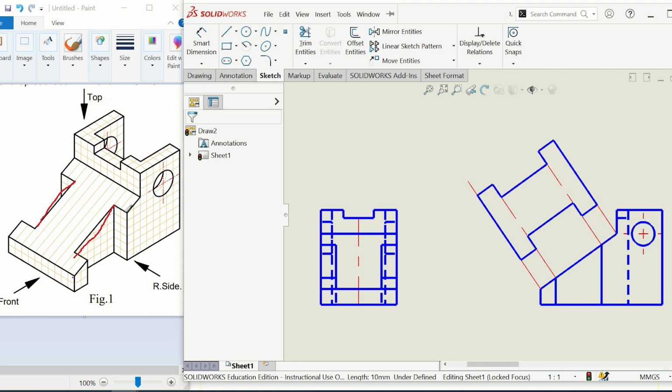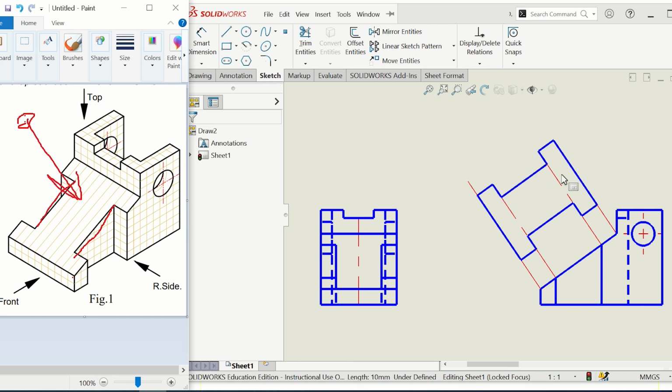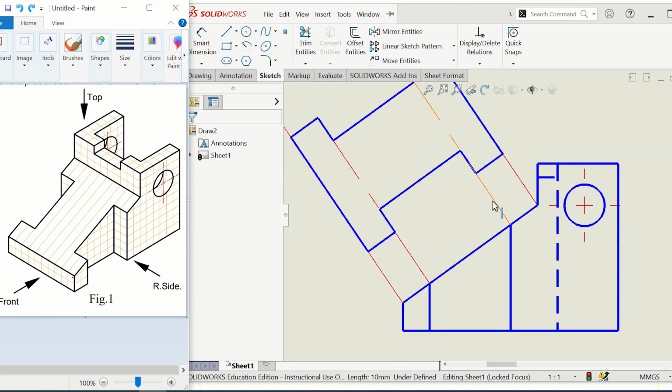projected to those planes. Whereas here, the auxiliary viewing plane, which as I told you is where we are here, these are our eyes, and we are looking perpendicular to this surface. So this eye shape is perpendicular to my viewing plane, and thus it doesn't lose any correct dimensions when projected to that plane. Now, for these lines here, the construction lines, you can keep them.